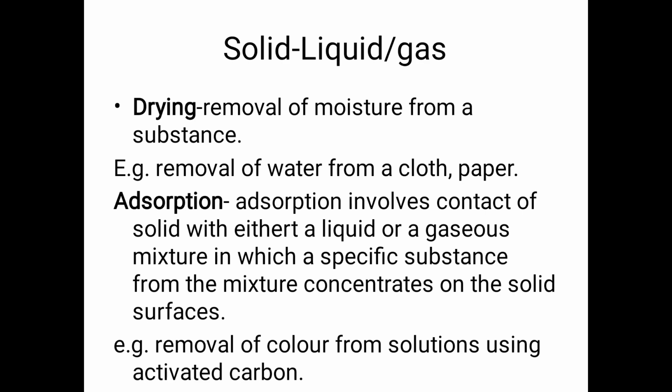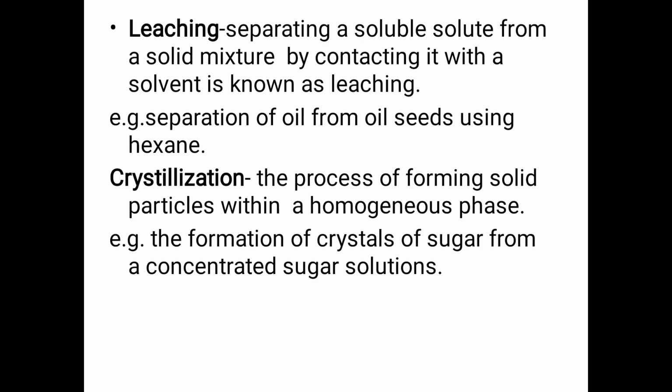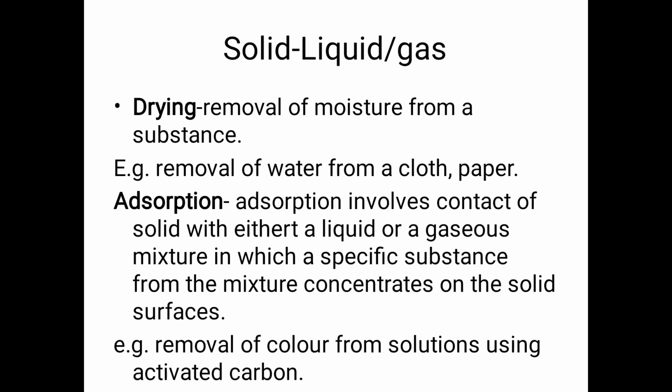Next, we move on to solid-liquid or gas operations. This operation involves three phases: solid, liquid, and gas. For example, the processes are drying, adsorption, leaching, and crystallization. Drying is the removal of moisture from a substance. Example: removal of water from cloth or paper.